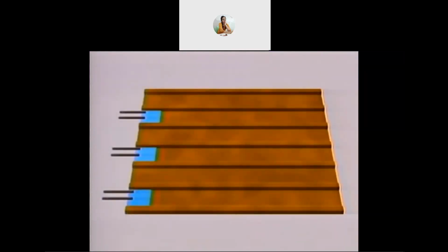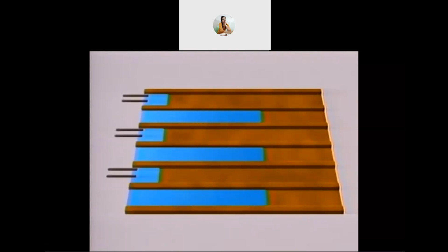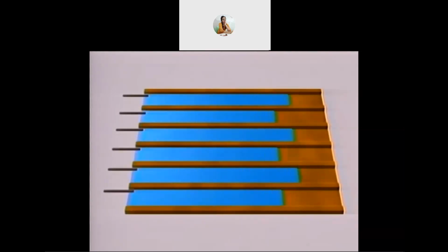An easier alternative is to put 2 tubes in every other row of your set. When the water is 2/3 of the way down the field, you move the double tubes to the dry row. When the water is 2/3 of the way down the row, you move 1 tube back to your original row.